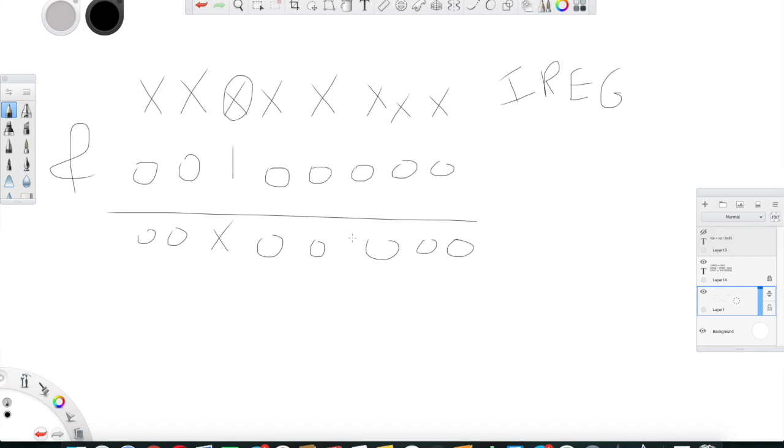Now I need to what? I need to compare. Okay, I can compare for equality. If the button is pressed, it means what? That X should be 0. So I can compare it with 0b and zeros, or actually it would be easier to write 0x00. Okay, or I actually can negate the mask, but let's do it simple.